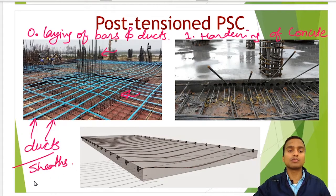Through these ducts we will pass the tendons later on when the concrete is hardened. After laying down these bars and ducts, we pour concrete on it and allow it to harden completely. And when the concrete is hardened, then through these duct spaces we pass all these tendons.